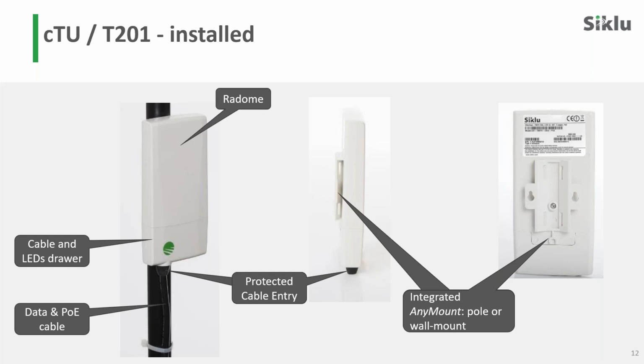They are black. That's the only way it is possible to get a tie wrap which would be UV resistant. If you see other equipment where the tie wraps are not black, they are generally not UV rated, and basically they will drop after the first summer.